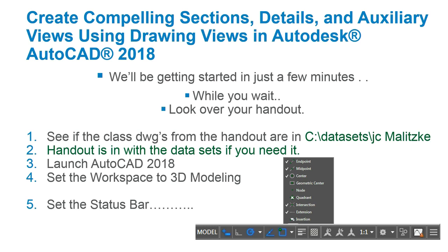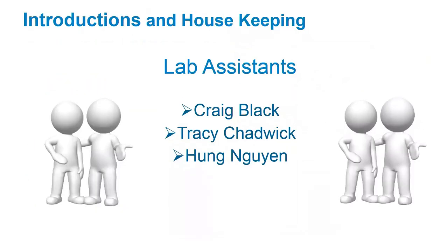Okay, so we want to have these 4 turned on. We don't use ortho anymore. We use tracking with our polar tracking set to 90, and only use ortho when we really need it. Ortho is like a superseded command. I'm going to move on.